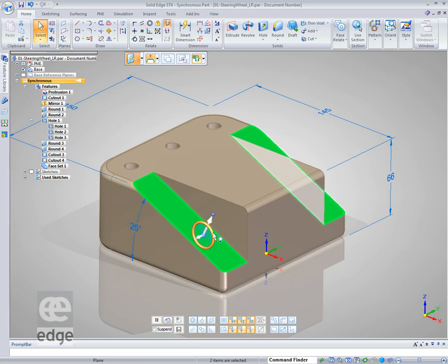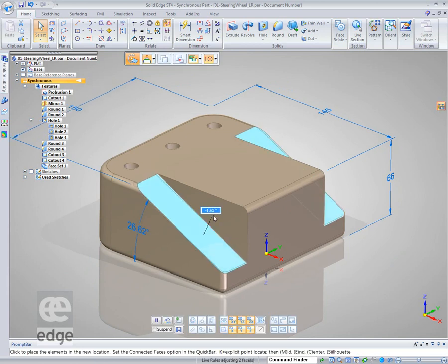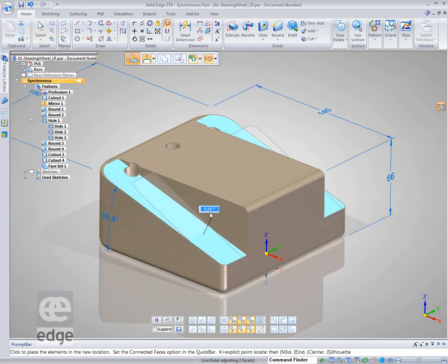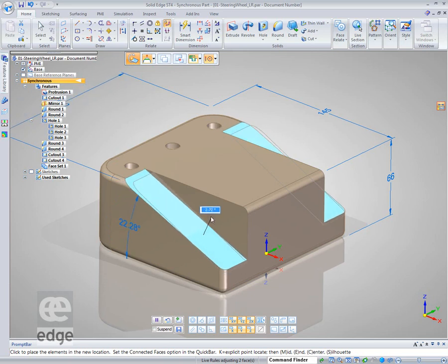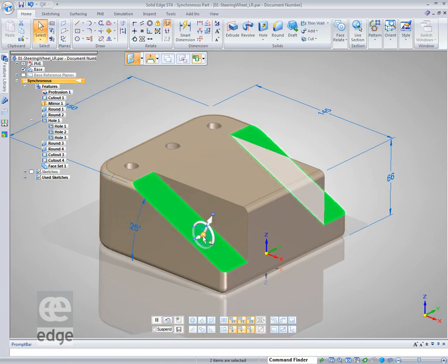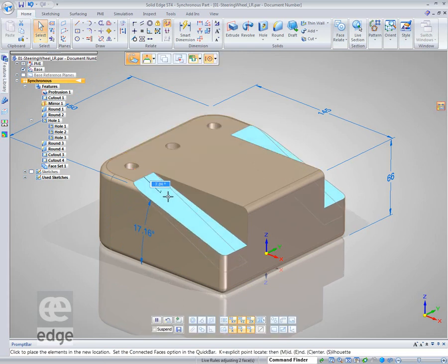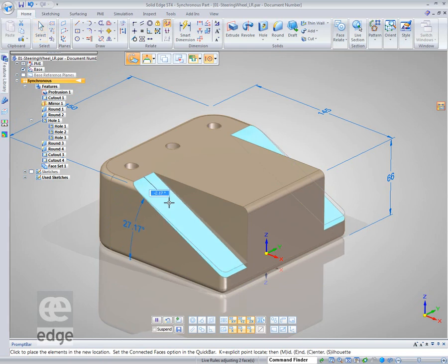What's going to happen if I click on the steering wheel and rotate it? We'll see both those faces, because I selected both those faces, will update. Let's move the steering wheel, so we pick the origin, and I want to move it up just to that edge up there. It happens to be on the center of that edge as well. You saw the center glyph come on. And I can rotate it again.